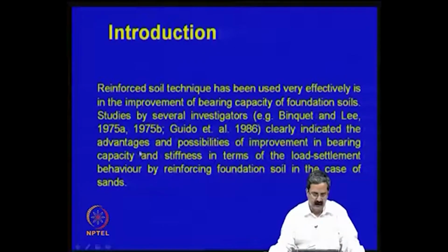They were clearly able to bring out the advantages and possibilities of the improvement of bearing capacity and stiffness in terms of the load displacement behavior or load settlement behavior, because we try to do a plate load test. A simple case is that you do a plate load test on a typical soil and then put the reinforcement and again do a plate load test, to see how it can improve. So, in this class today we would be talking about bearing capacity improvement in the case of sands.